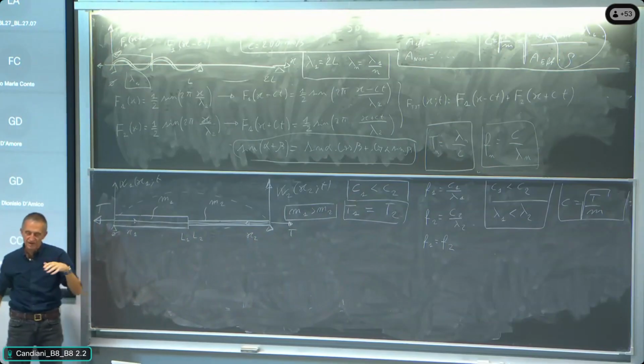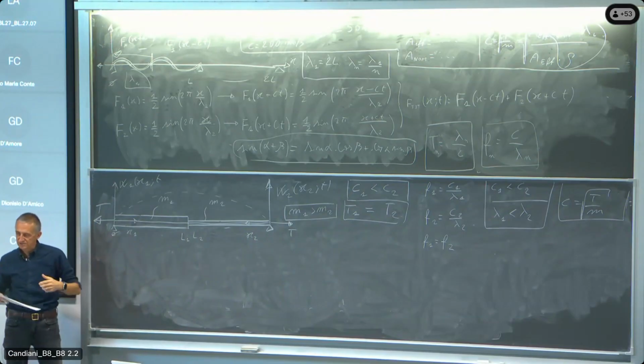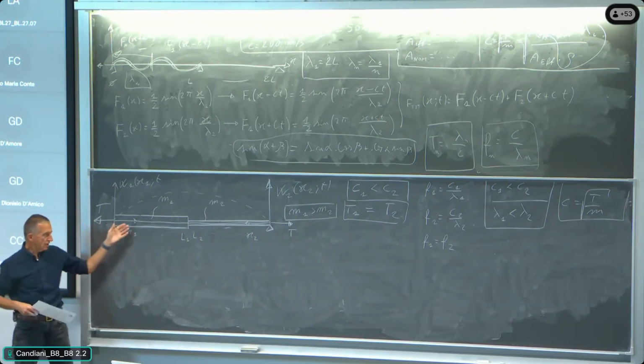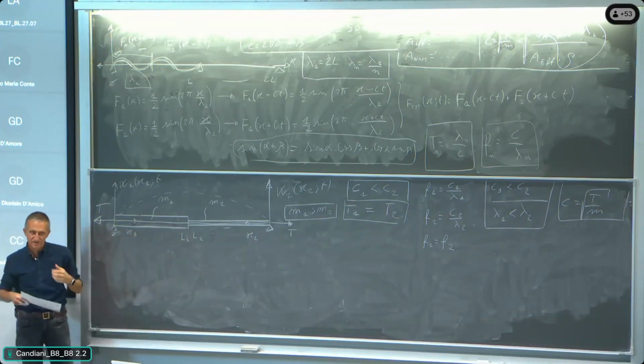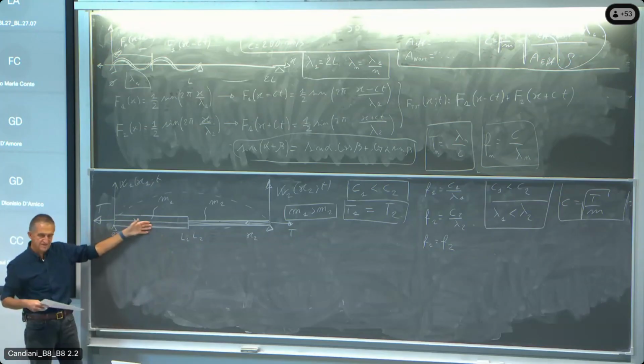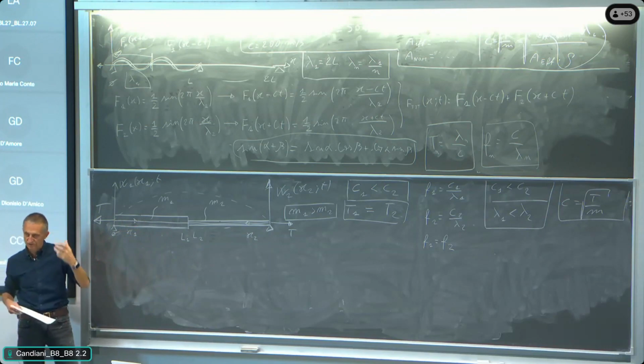the vibrations are always made by a competition between the stiffness and the inertia. The stiffness is given by the tension. The inertia is given by the mass. The two objects are sharing exactly the same tension, so they are sharing the same stiffness, but the mass is larger here and the frequency is lower. So we must have this intuitive vision of the vibration.